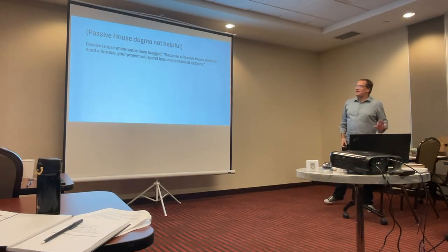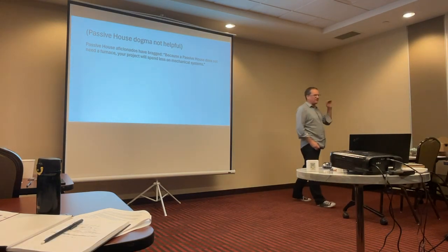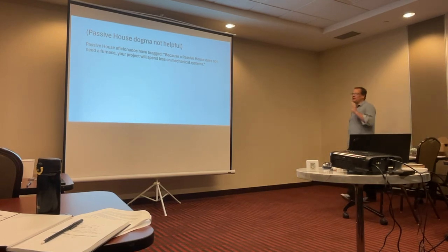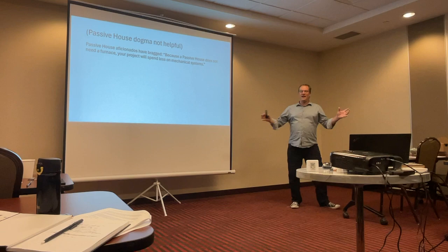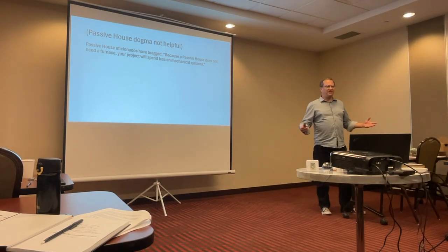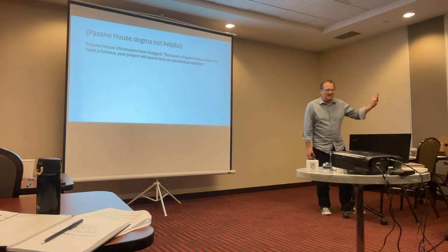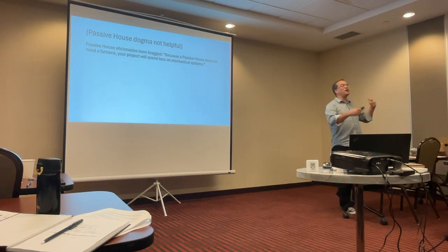Okay, and I think this is really important for those of you who are coming from single family or coming up with Passivhaus dogma: it does not help on multifamily. For years and years, Passivhaus aficionados have gone around saying, oh, you're not going to spend much on mechanical and you're going to make it up on the enclosure. But a multifamily building has been 1 bathroom fan and 2 baseboards for as long as I've been alive. What is cheaper than 1 bathroom fan and 2 electric baseboards? There is nothing cheaper than that. It's going to go up a lot.